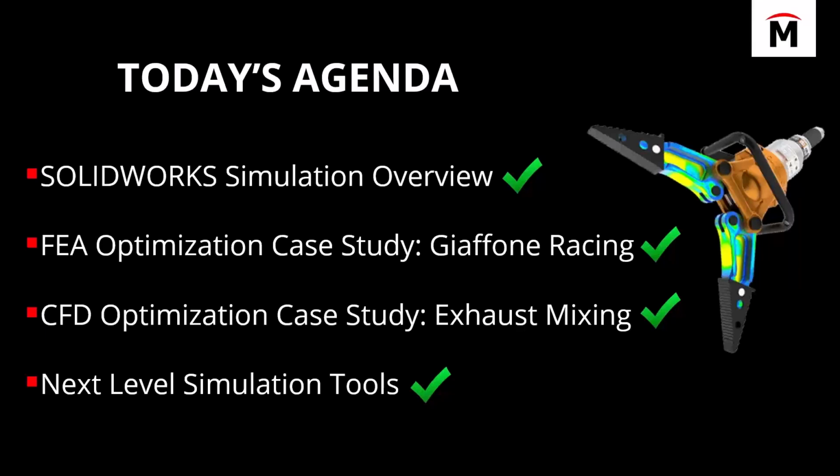But I'm also doing other stuff on my computer at the same time the sim is running. So I'd usually say buy more CPU speed and less cores. If you go out and buy 32 cores and you're just running SolidWorks FEA, you're going to have diminishing returns on that for sure. After about 8, I think it falls off. RAM for sure, just buy it. 32 gigs, I think you'll be in a pretty happy spot. I see machines with 64 a lot now.